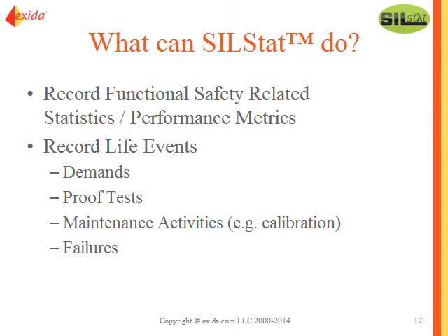So we can record live events, demands, the frequency at which a hazard occurs. And I will show you we can record what layer of protection is successful and what layer fails, if any fail. We record proof tests. Obviously we do proof tests to determine if there are any failures that were unrevealed during normal operation. Can we detect any failures that were not detected by automatic diagnostics during normal operation? And we're looking at recording any failures, having that data.